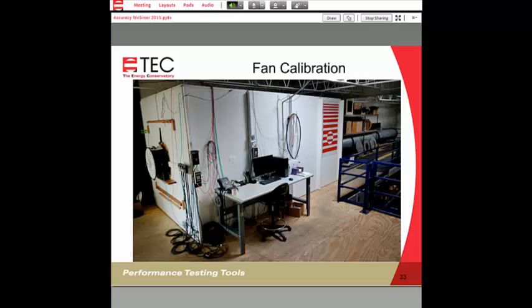Those screens, then this box enters into a long cylinder that you see on the right-hand side, a piece of ductwork, and lying against that ductwork are orifice plates. Those orifice plates are the pressure measurement standard. So we are able to put different orifice plates in this flow area of the ductwork, and we measure across that and compare how the fan compares to all those values.